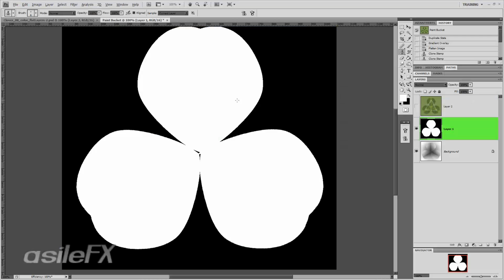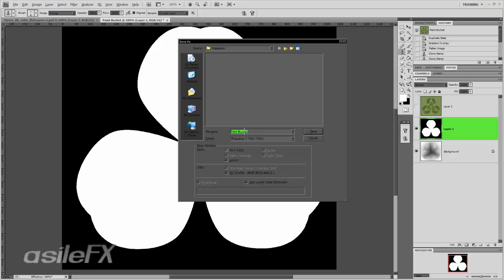So one thing to keep in mind is if 16-bit TIFF isn't working, try a different format. I know that there are some issues with Mac. At least I've had a couple of clients opening some of my TIFF files that were 16-bit and them not working, so then having to use different formats. PNG works pretty well. You can always go to EXR if needed. Of course, that's 32-bit, and extra information that may not be needed. So now I'm going to save.